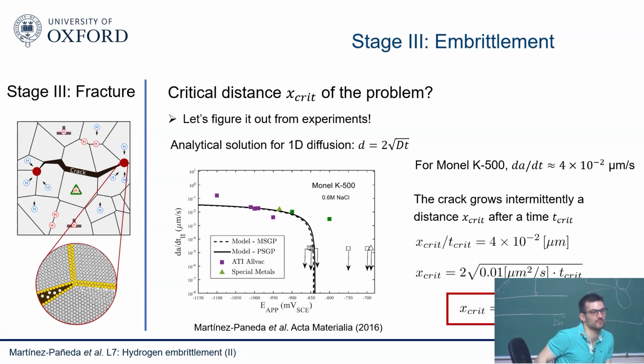If I look at it from another perspective, is it correct to say that in the time frame that you are looking at, accounting for the diffusivity of hydrogen, hydrogen is actually capable of moving 1 micron? Yes. Even though based on my crack velocity being 4 × 10⁻² microns per second, my crack is only growing roughly almost 1/100th of that, hydrogen is able to move 1 micron.